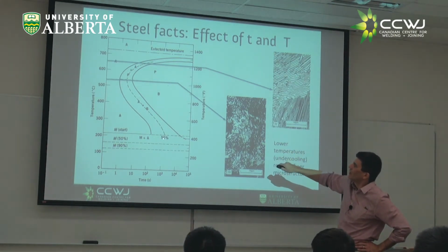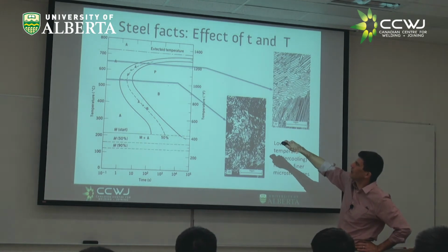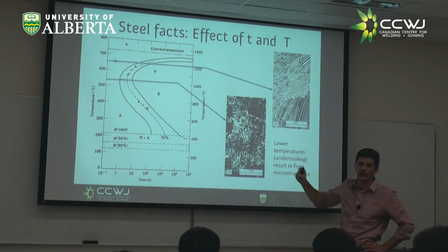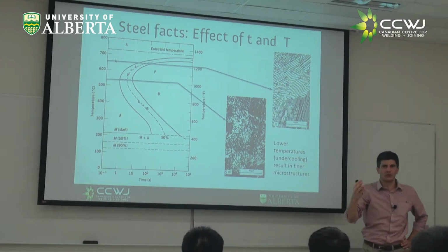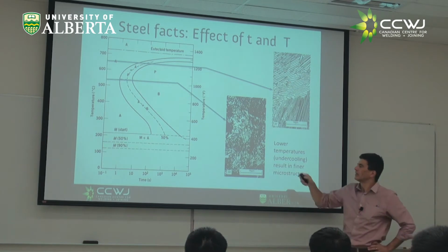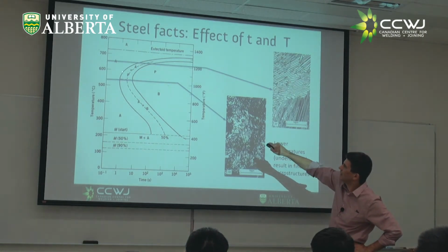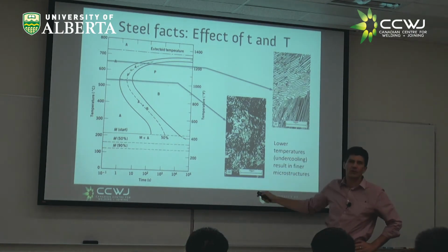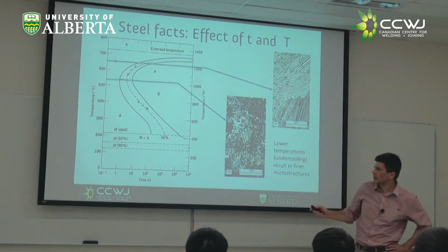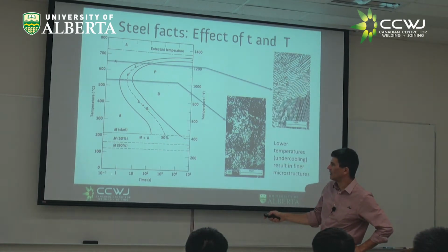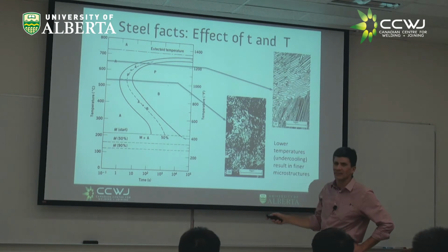So what is this curve that says, well, if we go from austenite to 800, or from austenite to 600, or austenite to 400, this experiment I mentioned, and you hold, the horizontal axis is time. This would be my start time. This would be my finish time, right? And this is in log scale. So you realize that this is 10 times lower than this, and this 10 times lower than this, right?